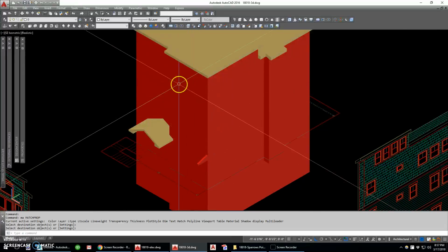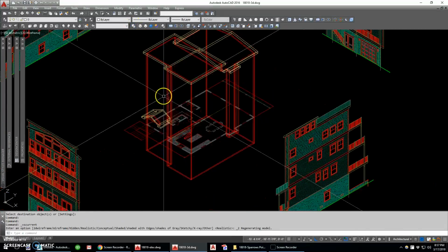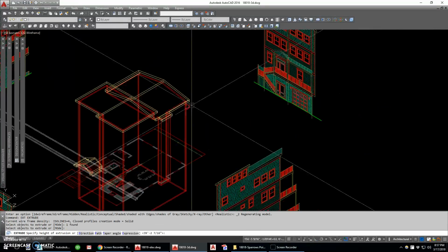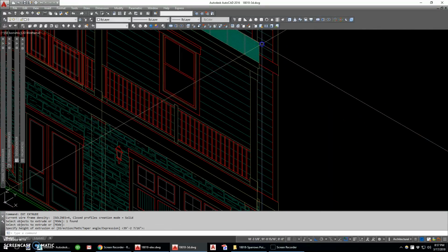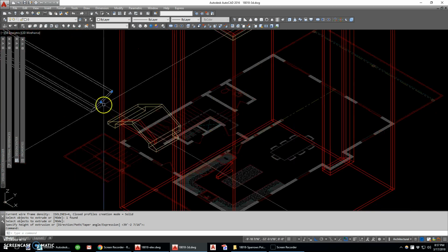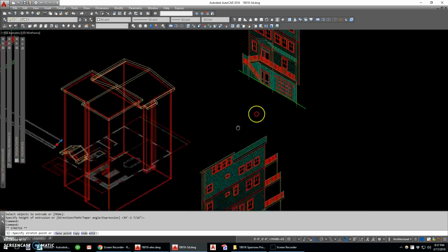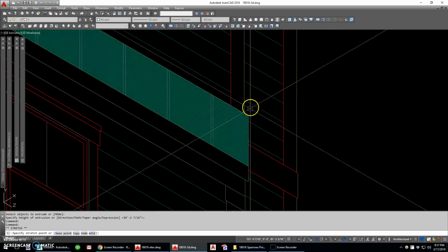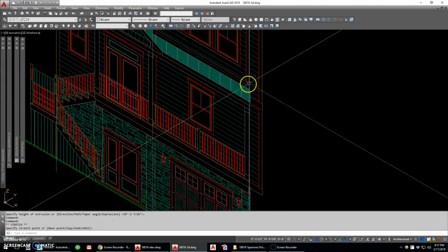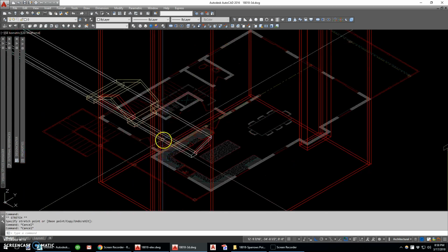Now we need this side piece of roof. I've got 1 minute. Let's see if we can do it. Here's my side roof. I'm going to extrude it, use my elevation as a reference. I think I clicked it. Oh, nope. I'm actually going to click this little node and drag it. It stays planar, going in the same direction, and use this as a reference. Now it's out where it needs to be.